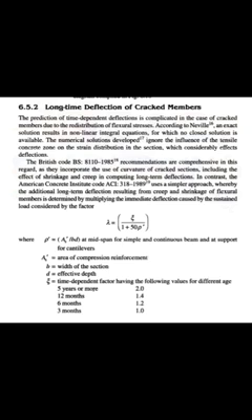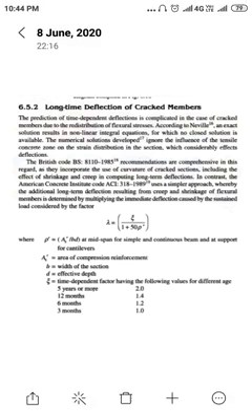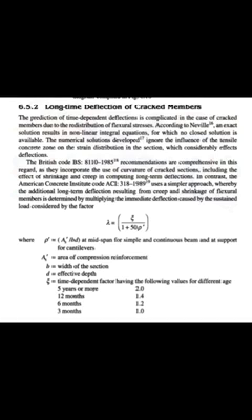According to the British Standards Code recommendations, the curvature of the cracked section is used, in which the effect of shrinkage and creep on the long-term deflection is considered.